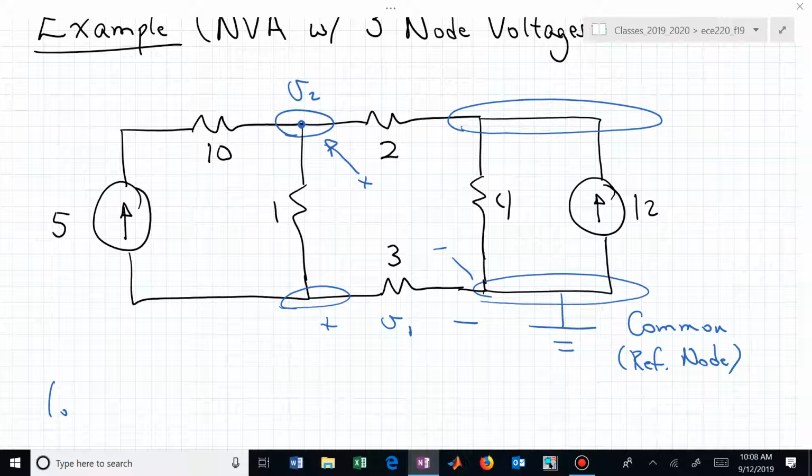How would I find, well, this is kind of getting aside, but can you find the voltage across that 1 ohm resistor in terms of the labels I've attached to the circuit now? From top to bottom, it's just V2 minus V1. That's the voltage dropped across that 1 ohm resistor, going from top to bottom. What about the last essential node?